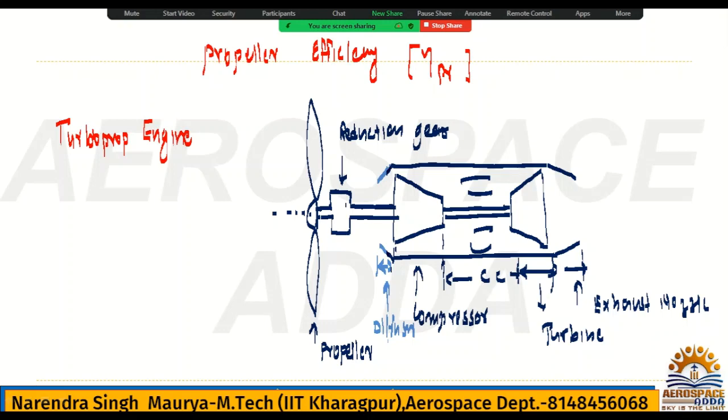So if it is reaching sonic speed, then somewhere there is the critical Mach number. Critical Mach number means somewhere on the blade the flow will be sonic flow, and then shock bubbles will start forming and shock will be formed. Because of that, there will be aerodynamic losses, and there will be chances of stalling of the flow from the blades.